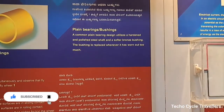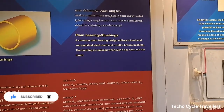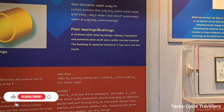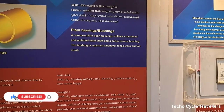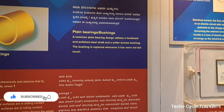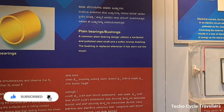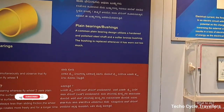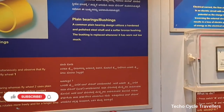Plain bearing bushing. A common plain bearing design utilizes a hardened and polished steel shaft and a softer bronze bushing. The bushings are replaced whenever they have worn out too much.